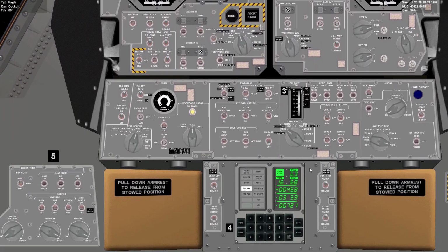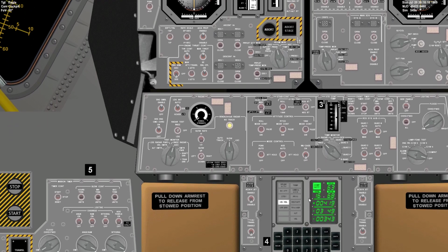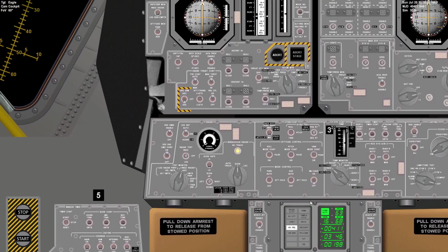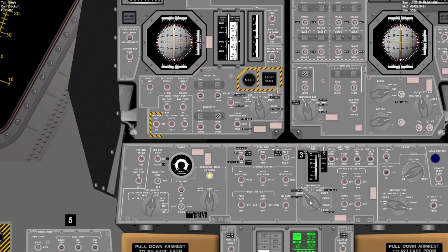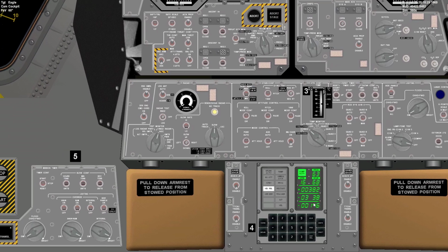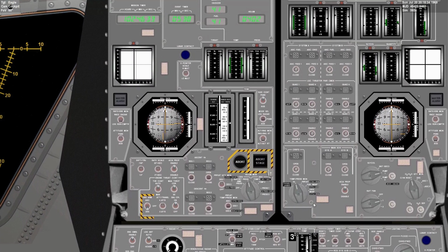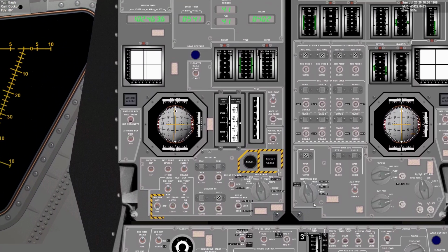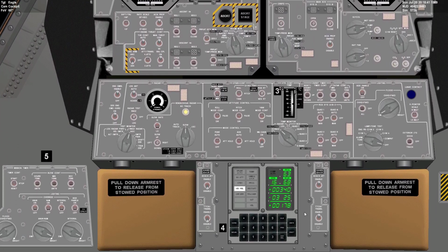What that lets me do is, instead of using a peripheral instruction to poke a value inside the AGC, I instead can just poke the memory inside the FPGA and just give the AGC the updated value when it asks for it. So it's much more seamless. All of the problems magically disappear when I do that. So that's probably how we're going to end up operating, through simulated erasable.